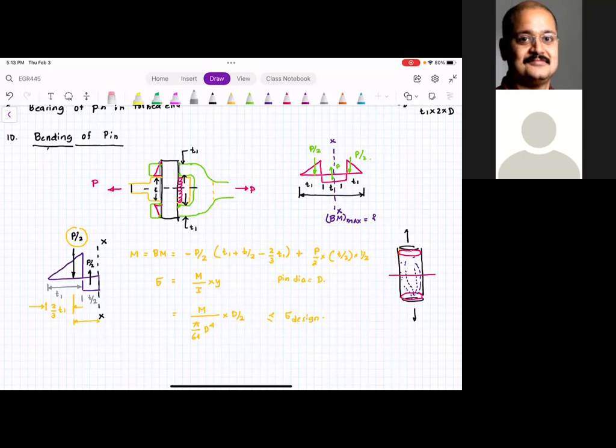And what would be the purpose of this deformable sleeve? This is what you will see if you look at the vehicle chassis, look at the bearing, that is where the bushing goes inside. You would add some sort of a liner, some sort of a bush. The purpose of that bush would be just to deform. It could be something like brass. The only function of it is to deform and make that surface smooth. So that would minimize the contact stresses, and that would actually increase the longevity of the joint.